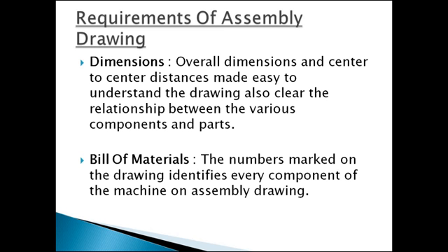In front of every component, if there is a pin, what is the material, whether it is steel, we write that in front of the name. And after this, how many components we have used: if we have used a single one, we show number 1; if used 2 times, we show number 2; if 3 times, we show 3.